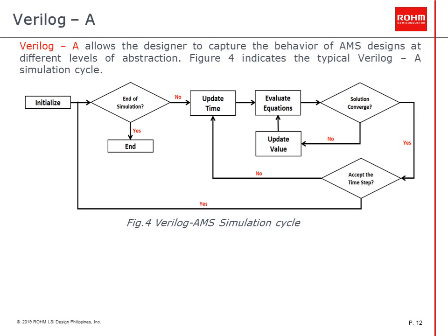Evaluation. The design description consists of differential and nonlinear equations which are discretized and solved iteratively. Update. Analog processes are sensitive to changes in all variables and digital signals read by the process unless that access is only in statements guarded by event expressions. Upon waking up, the process computes a new solution point, schedules its next wake-up event appropriately and then deactivates itself.